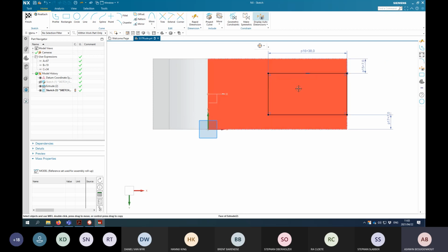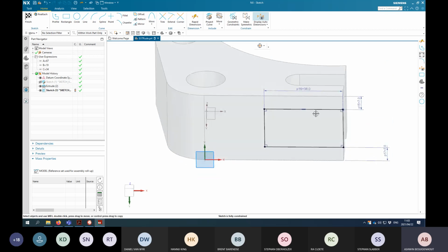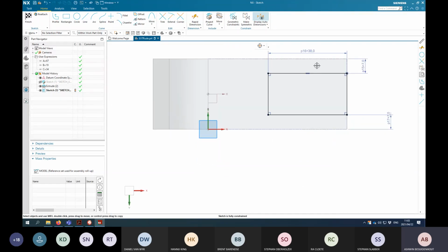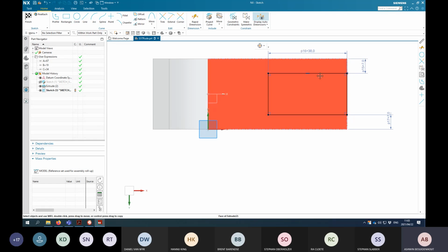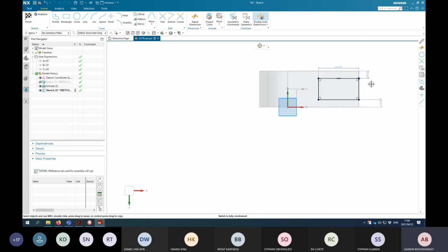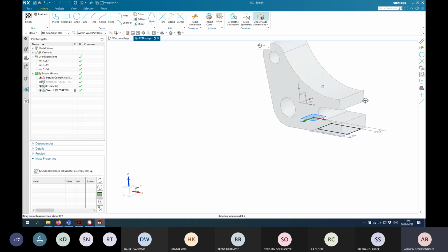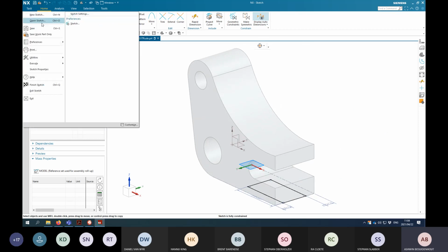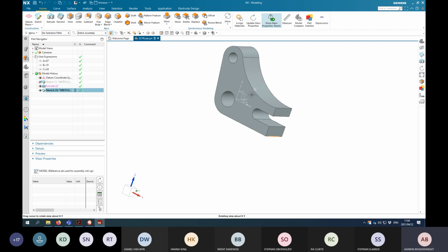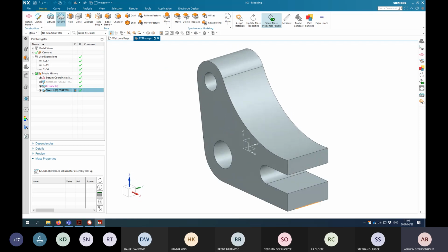You see what makes the sketching on this specific surface nice is that you have a fully constrained sketch, and all of the dimensions that govern that cutout are in one sketch. So if I need to edit something, I know I just have to go to one sketch. I don't have to worry about other sketches and how it works. So I can just go to finish up here. It's fine. I don't want it that way. And I have it symmetric.